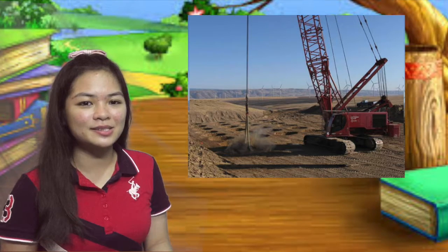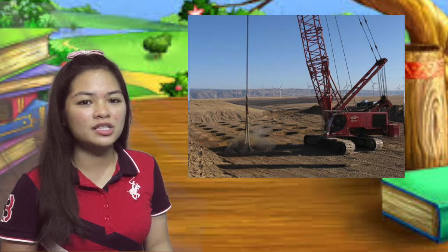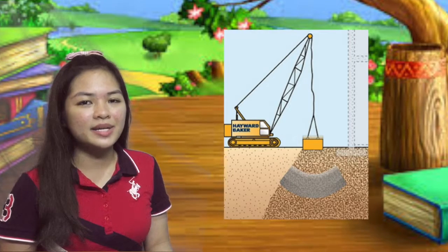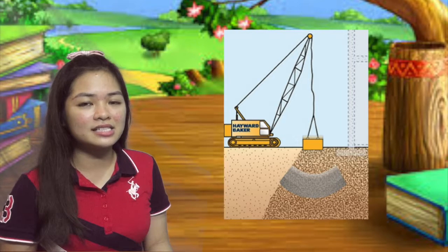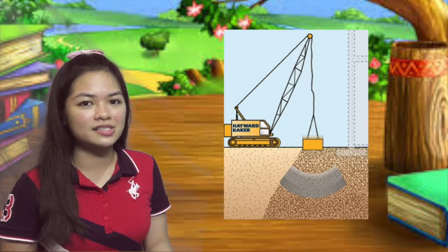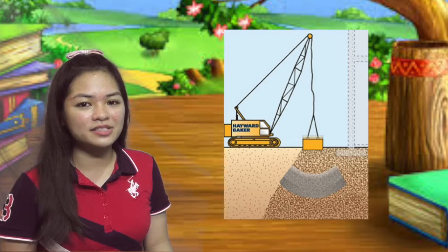The weight and the height determine the amount of compaction that would occur. The weight that is used depends on the degree of compaction desired and is between 8 ton to 36 ton. The height varies from 1 meter to 30 meters.